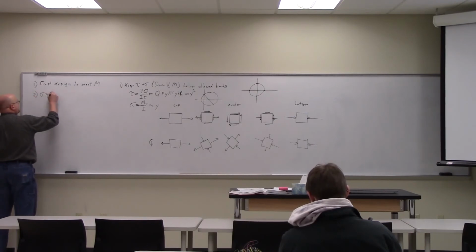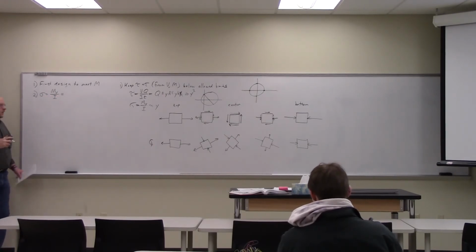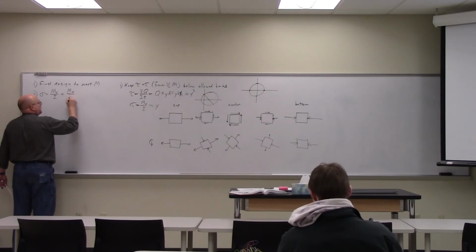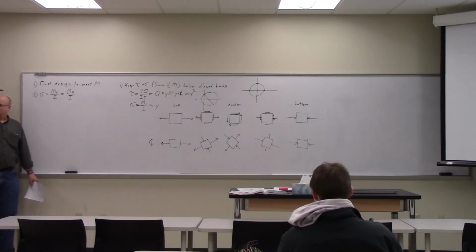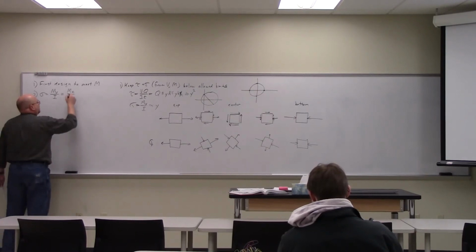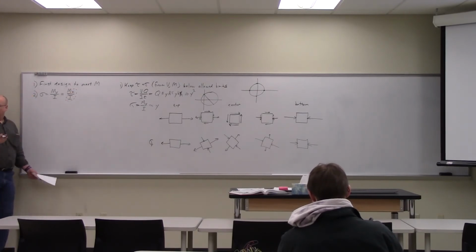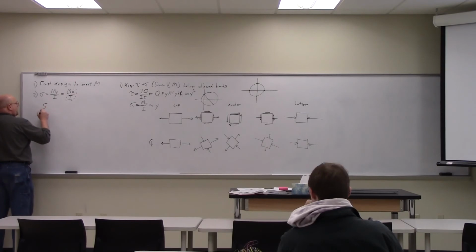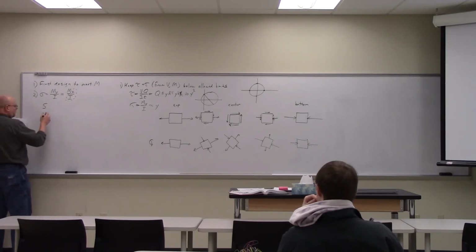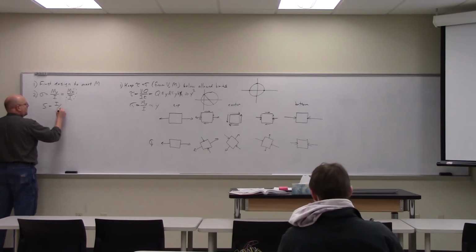So we have sigma equals M y over I. Where are we going to care about this? Where's the maximum value of this going to be? Right. So remember the book said M c over I. c is the maximum extent of the y direction. These are the geometrical constraints of the beam. And c and I are the properties of the beam. M is the applied load. So we're going to define a section modulus S that is I over c.